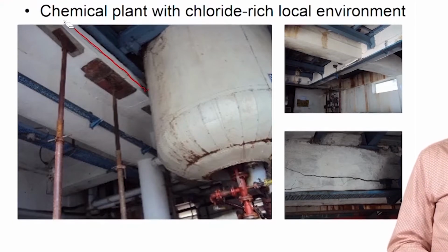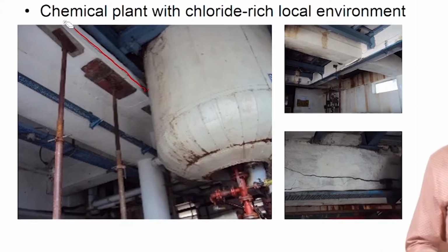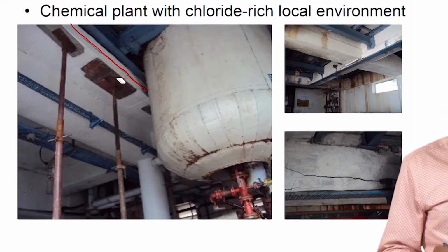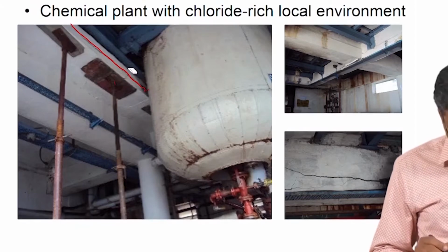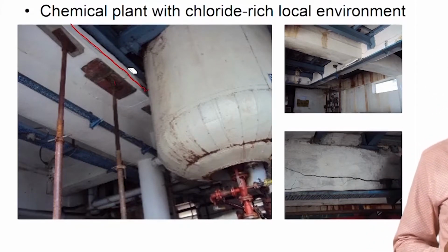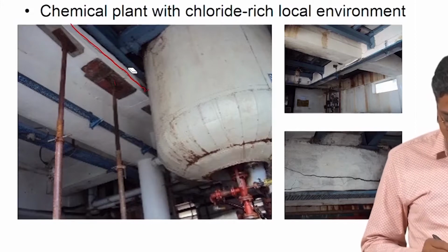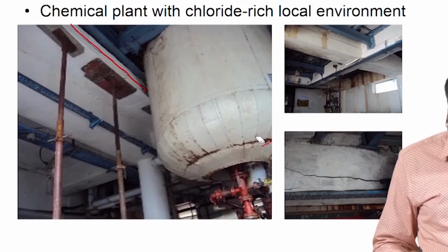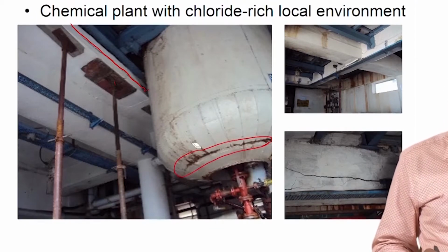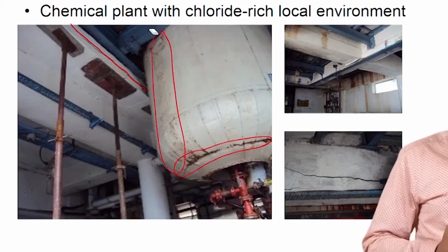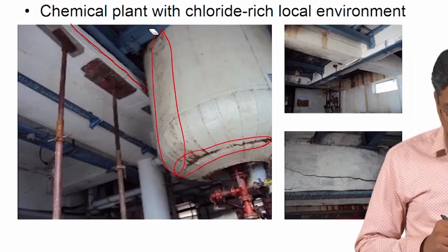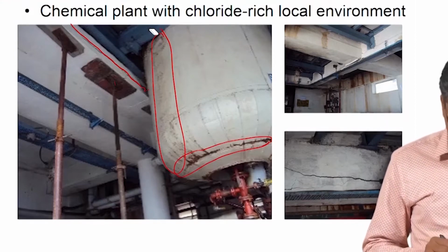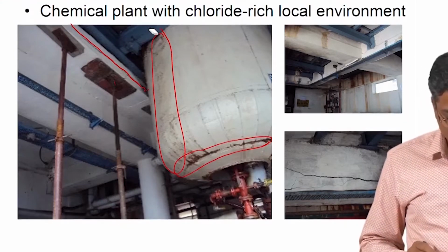And unfortunately this is not at all a safe practice, but I had this photo, so I thought of sharing this. You can see this propping, just prop support, it is not really a safe practice. You should replace the beam or do proper protection, and there are many cases where such unsafe practices do happen. And you can see even this tank over here is also corroding. So the safety of the workers who are working here is really not considered in a good manner, I would say. So that is something which we have to stop.